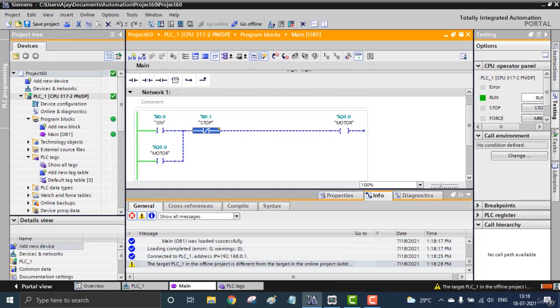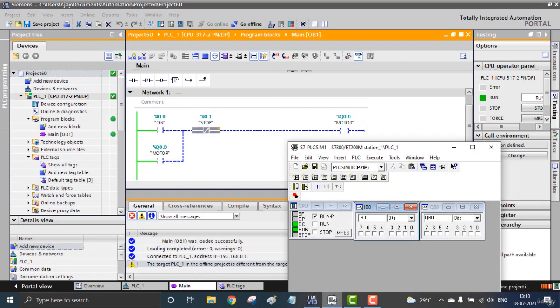So for the latching, you can see I0.0 will be the start button, on and off. That means press and release. It's a push button for starting the motor. That is the default starter concept. And you can go to I0.1 for stopping that, on and off. So that is the I/O addressing for the Siemens, and we can examine several more contacts and coils.